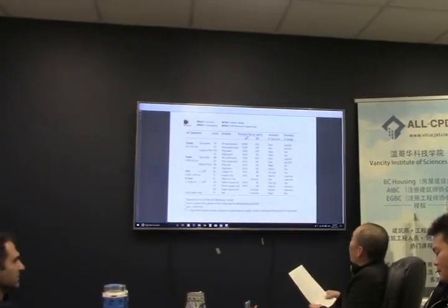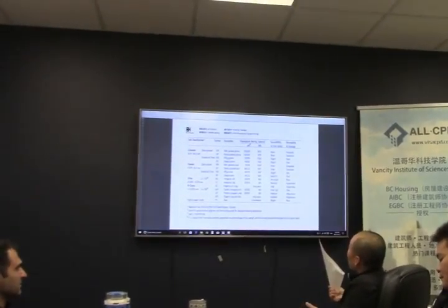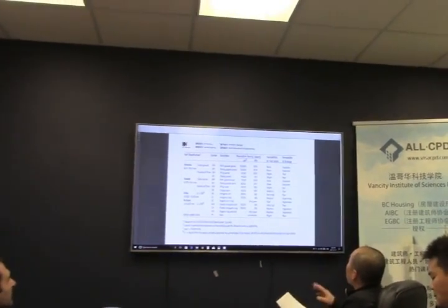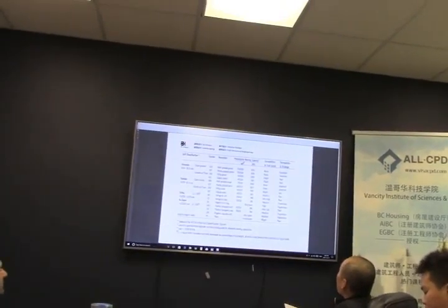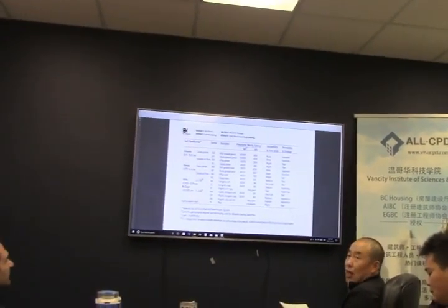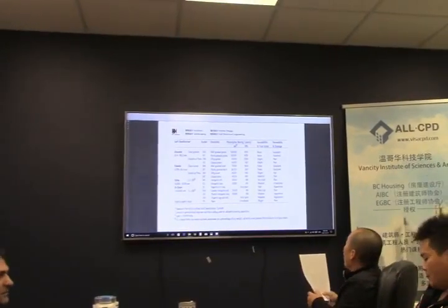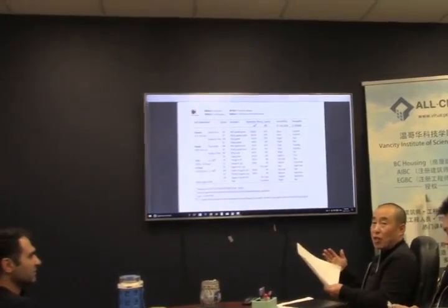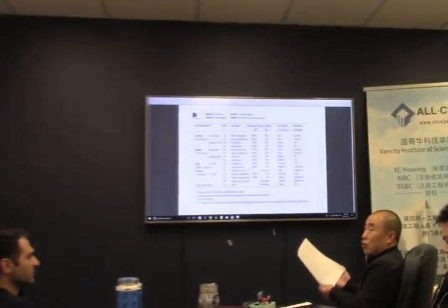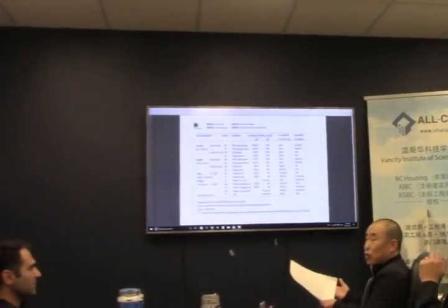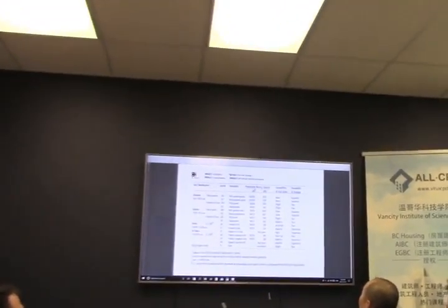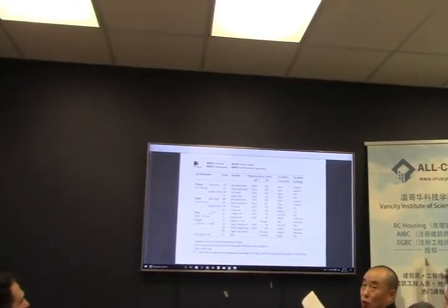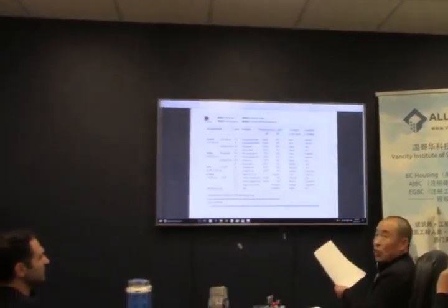The bearing capacity for gravel is almost around 500 kPa. And there's another characteristic, susceptibility to frost action. We can see gravel is not very susceptible to frost in the winter; for gravel it is none. Another characteristic is that it is permeable to water, so the drainage for gravel is excellent.